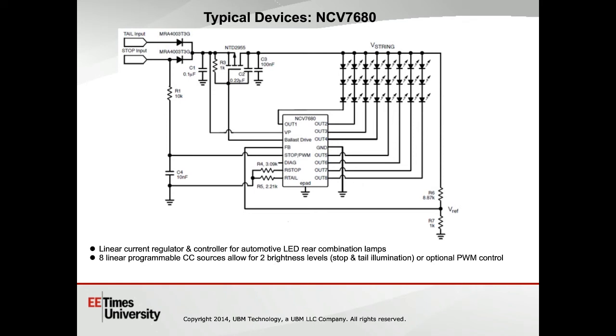It also has built-in protections like most of the devices we've talked about. These include current limit, thermal limit, and detection of open LED strings. And there's a diagnostic pin that is used to report the failures that it detects.